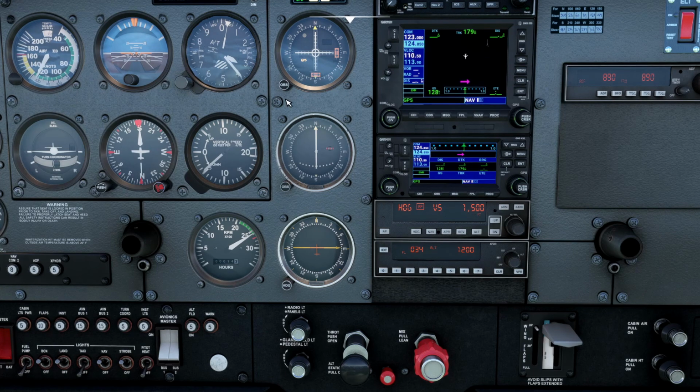Eventually, because I am descending and I'm going to encounter that altitude, it will automatically capture that altitude and then revert to altitude hold mode when I get to that altitude. If, however, I put in an altitude that's higher than my current altitude, I'm never going to get to that altitude while I'm doing a descent. So the system is just going to continue the descent indefinitely until it hits the ground.